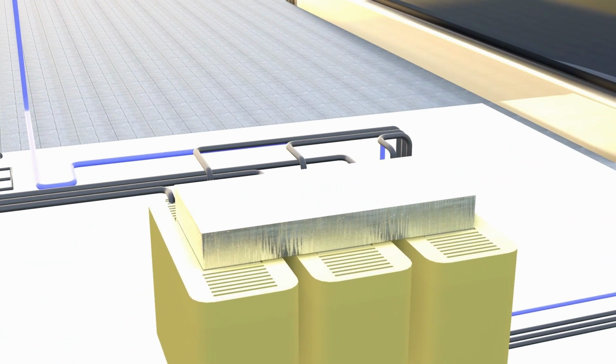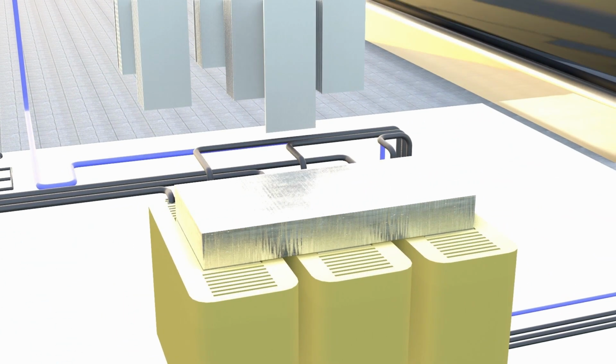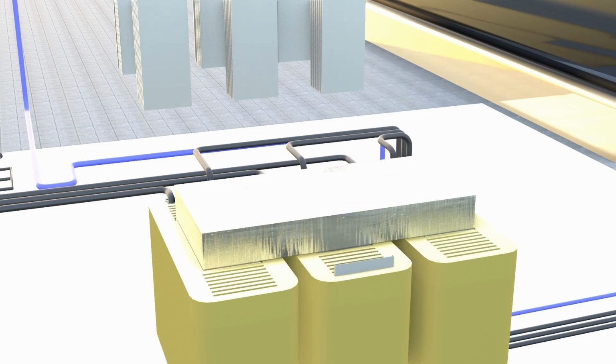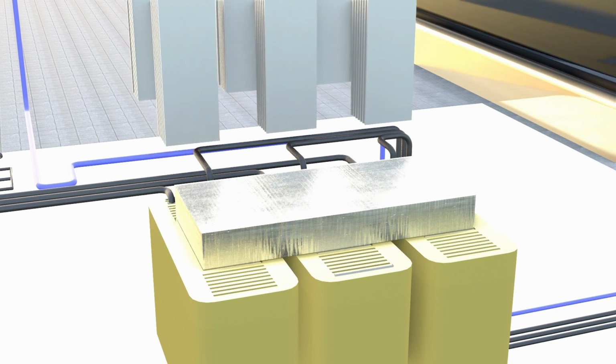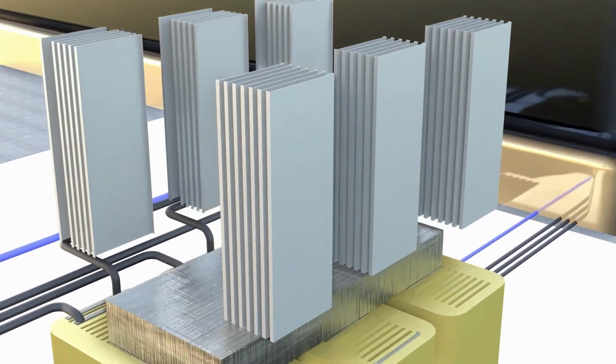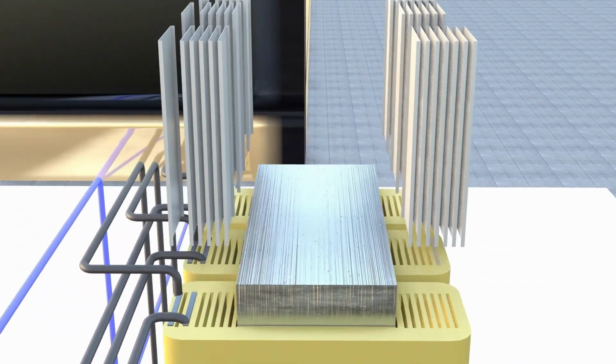In the subsequent step, a spacer plate is inserted into every air gap for the purpose of mechanical stabilization. These increase the mechanical strength, especially when strong forces occur, such as in short circuits in the power grid. Depending on the rated current size of the choke, the number of air gaps also varies, as well as the sizing of the spacer plates.